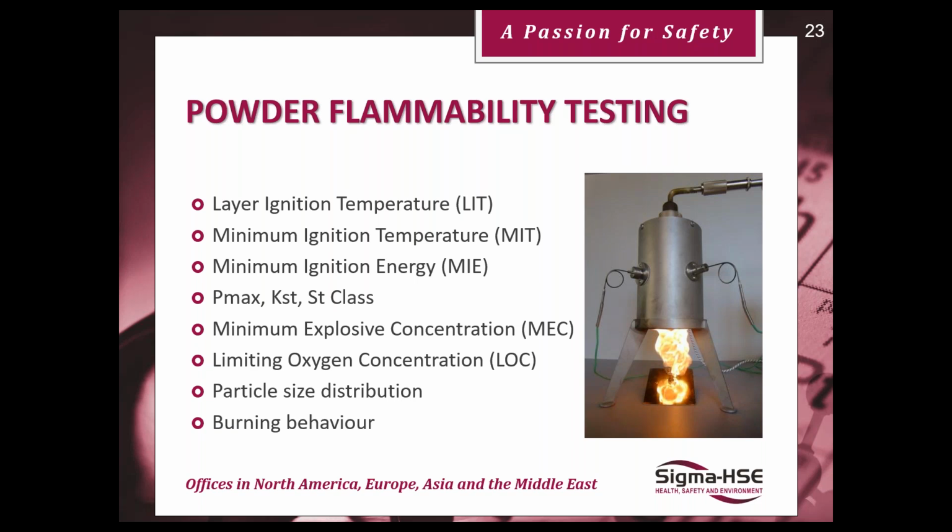If we understand the minimum explosive concentration, we can perhaps design our systems to operate where we keep the concentrations below the MEC, the minimum explosive concentration, or indeed the LEL if we're looking at vapors or gases. If we know the limiting oxygen concentration, we can start inerting our systems or working under vacuum to prevent ignition, and so on and so forth.